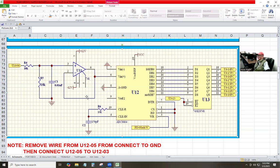It's not shown here, but you have to make sure you connect pin 20 to 5 volts and pin 10 must be ground. And in here, pin number 5, before they connected it to the ground, we corrected that.